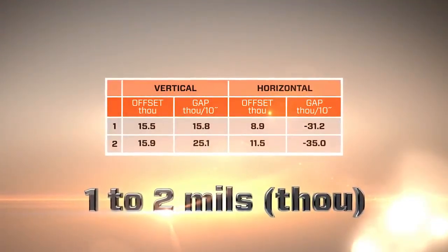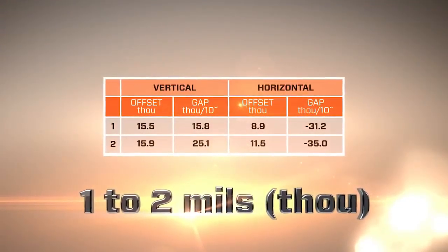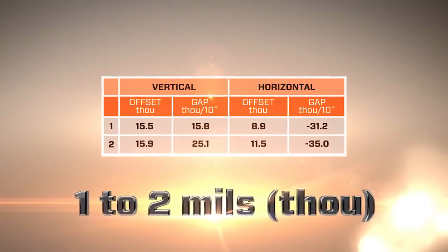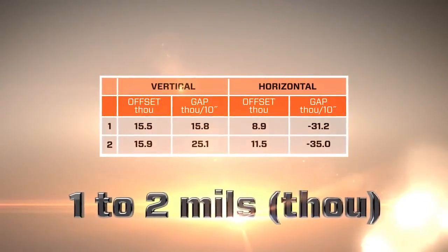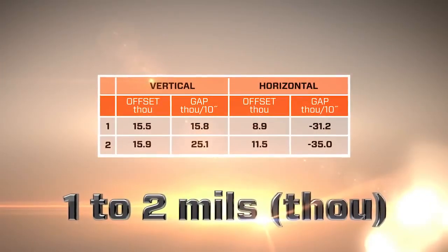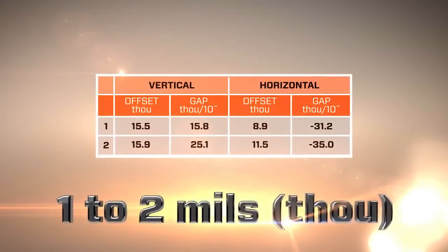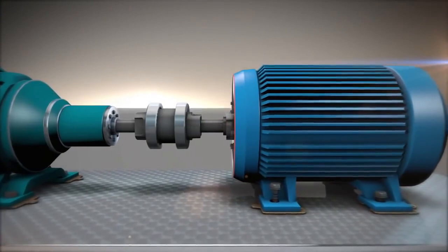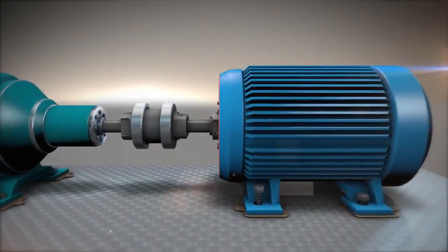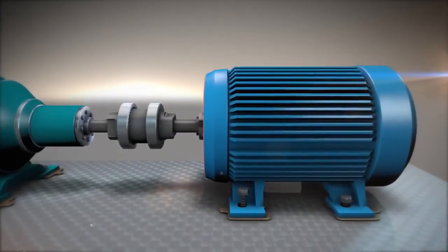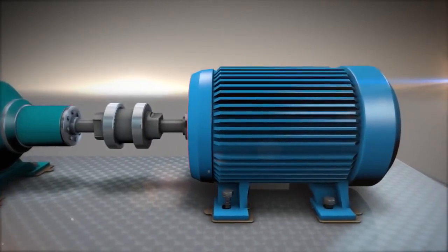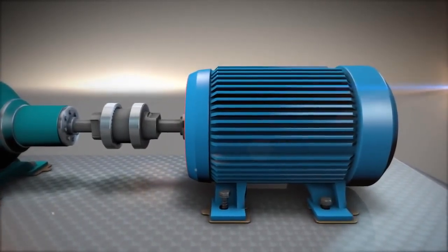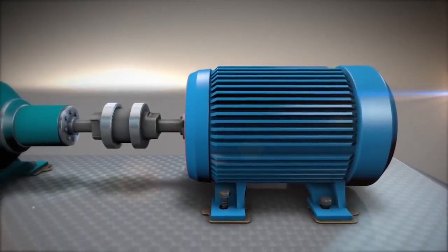Once rough alignment has been performed, the results should be no more than 1 or 2 thousandths apart, which is not the case in this example. It makes no sense to proceed with the alignment until and unless repeatable readings have been achieved. If repeatability is poor, there may be several root causes to consider, such as loose components, worn bearings, loose anchor bolts, and vibration from nearby machines, among other causes.